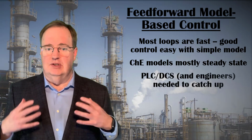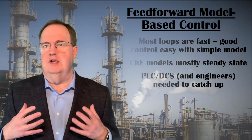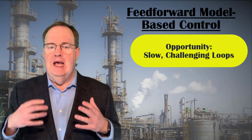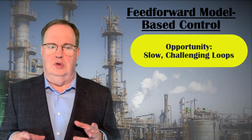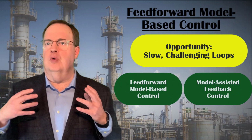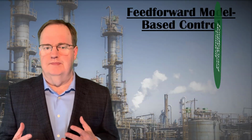And lastly, until the last decade or two, real-time computation was expensive, and process control computing devices were not designed to facilitate it. But there is a group of control problems where there are slow enough dynamics that control is challenging, and where even a steady-state model estimate can greatly assist our feedback controllers. The manner that we'll do this is labeled feedforward control in textbooks, but I prefer to call it feedforward model-based control or model-assisted feedback control to link back to our chemical engineering models.